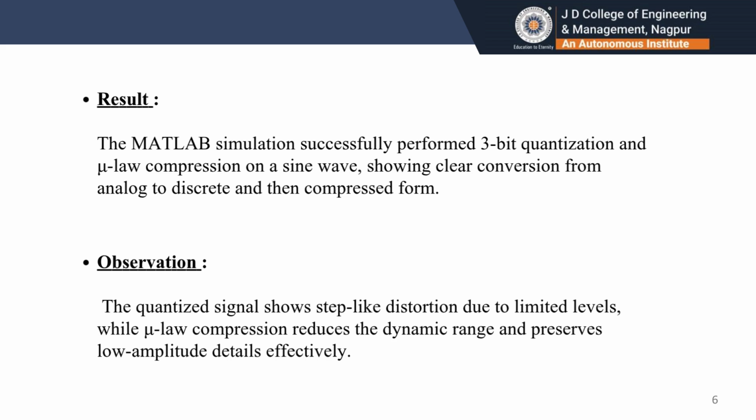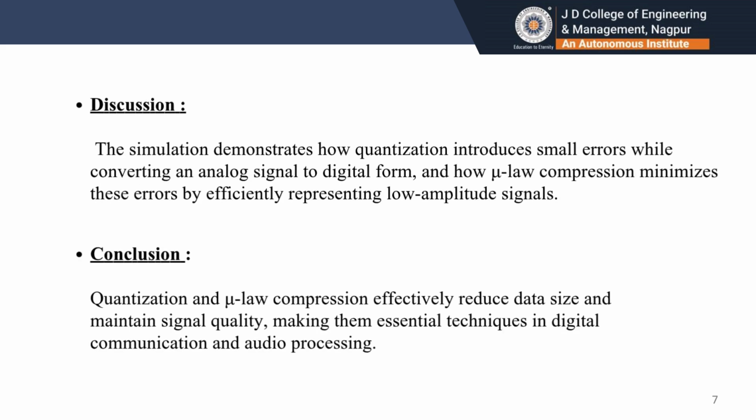When we observe the output, we notice that the compressed signal completes more cycles within the same time duration. This shows that the signal frequency has doubled, and the waveform appears shorter and faster in time. This behavior illustrates the concept of the time-frequency trade-off, which states that when a signal is compressed in time, its bandwidth increases in the frequency domain. In simple terms, faster signals require more bandwidth, whereas slower signals occupy less bandwidth.